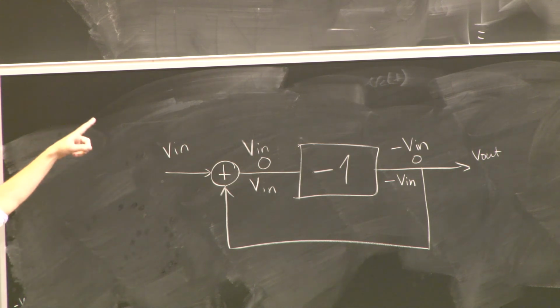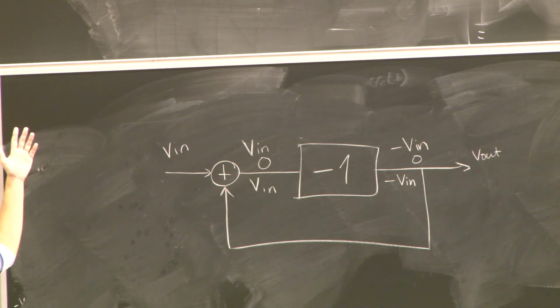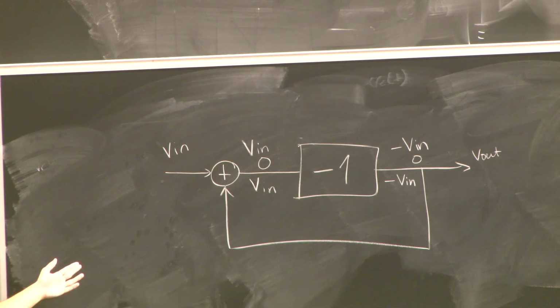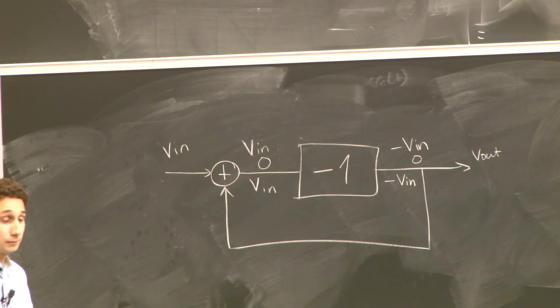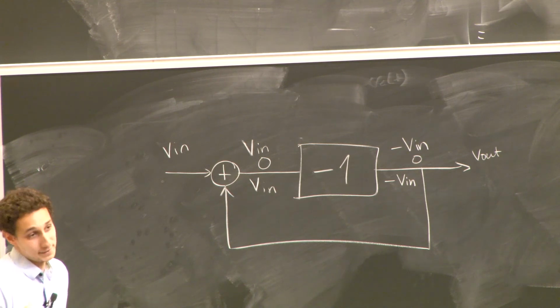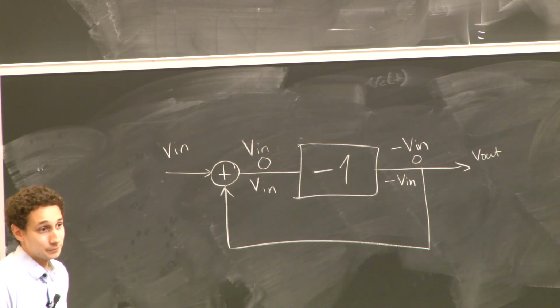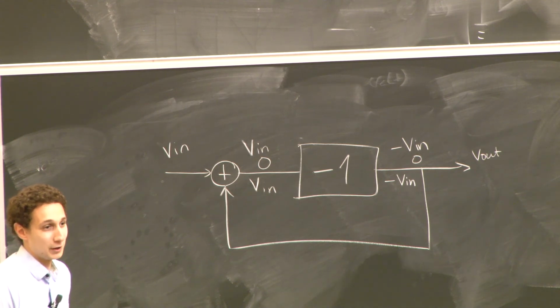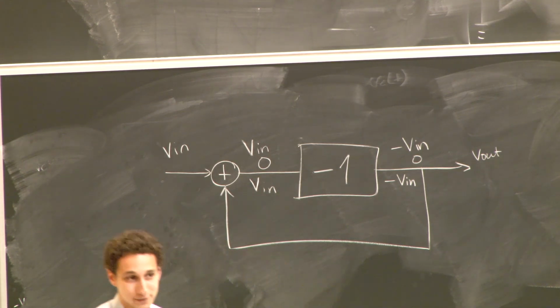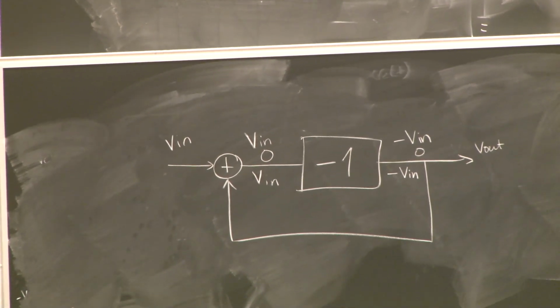In the previous one, where I had that exponential explosion, where my output voltage just kept going up and up and up, and I couldn't stop it, what do I know about the eigenvalue of that system? One of them is greater than 1, or less than -1. Actually, I know that it's greater than 1 in that case. You're right. Okay, cool. So circuits, again, comes back to this concept of linear algebra once we get into control circuits and feedback. Okay, it's all linked together.